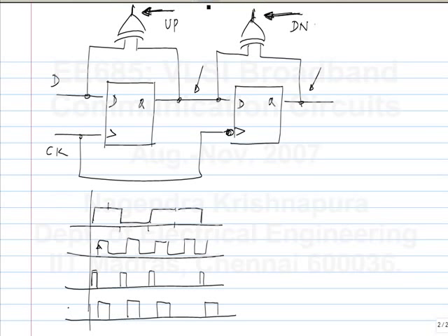Is this clear? If you understood the general principle of phase detection, there is not much complicated with this. You can take this phase detector, put it in place of the phase frequency detector, drive it with data, and it should be able to lock it.